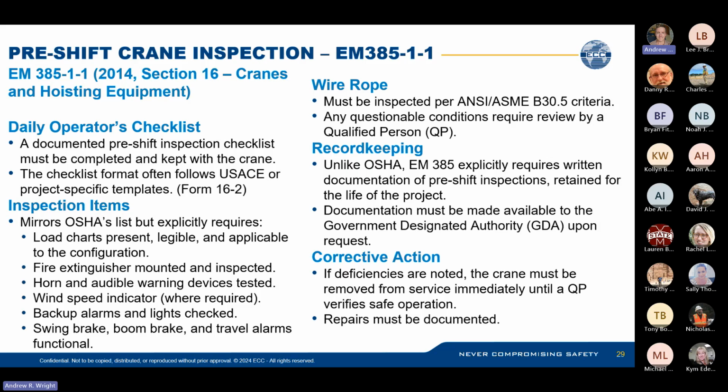Some inspection items, I'm not going to go over them all again, but some unique ones to the EM 385 is you've got to make sure the load charts are present, legible, and applicable to the configuration. They want you to inspect the fire extinguisher, that it's mounted and inspected, for its monthly service and its annual service as well. Make sure the horn and audible warning devices are tested.